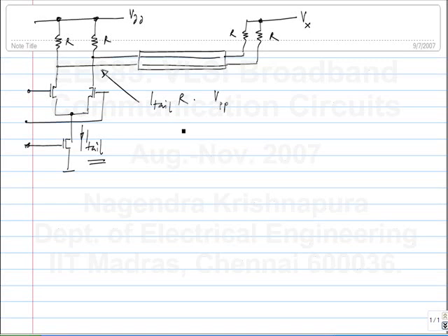Similarly, if you try to increase the number of taps in the equalizer or increase the magnitude of the taps, you will end up with the differential pair transistors in the triode region. Okay. And not only that, it also depends on the value of Vx that you connect it to. Okay. We looked at several choices. So the first one was to AC couple the transmitter output.